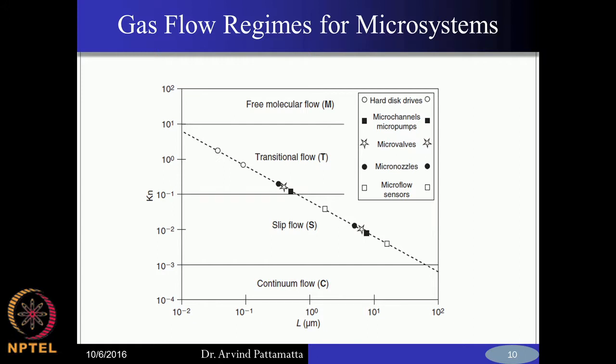You just solve your continuum equations with your normal no-slip boundary conditions, and this will predict perfectly well, no problem. So, when people talk about microchannels, you should not get carried away. There is nothing fancy in that. Most microchannels use liquids, because as you saw, the heat transfer coefficient is higher for liquids compared to gases, and therefore, for practical cooling applications, liquid is generally preferred, and in such a case there is nothing to worry about in terms of modeling. So, perfect continuum assumptions can be used.